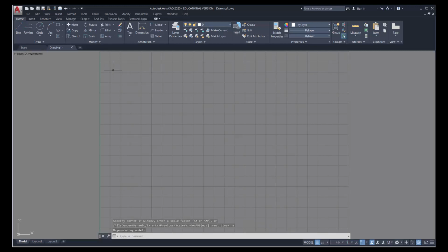So this is 12 units wide, 9 units tall. You may or may not have noticed when we typed in the command, we accepted the default as 12,9. What do those numbers mean? Those numbers refer to the absolute coordinates of the page in X and Y. And you can see the icon at the bottom. This is the coordinate system, or the UCS icon, which simply identifies that Y goes up and down and X goes horizontally. So when we type in values, we have to type in the horizontal value first and then the vertical value, or the X comes before the Y, just like in the alphabet, and we do the same here.